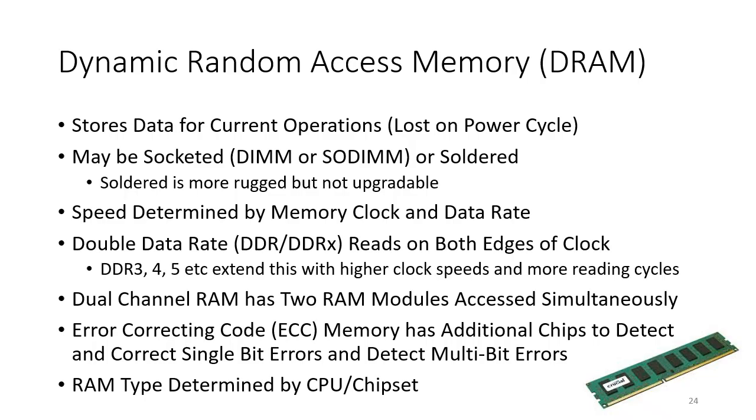But the downside is you can add more in terms of costs. You do need the connectors, and it's not as rugged. Yeah, I have seen applications where under high levels of shock, DIMM memory or SO-DIMM memory can actually be knocked out of the sockets. They're pretty rugged, but not perfect. So yeah, again, that's your choice, either socketed or soldered. And in an industrial PC, soldered would be your best choice.